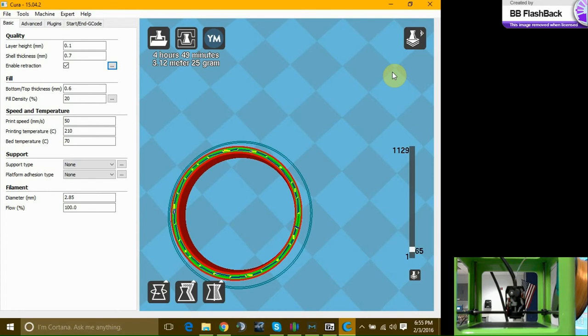25. So that's if you want to save weight, but then you'll be losing strength in a certain direction, because it will give a different pattern in the middle. 100% fill will have a plus 45 to a negative 45 pattern, 90 degrees off each other. So you have one layer, a unidirectional layout, where your filaments will do a zigzag in one direction, and the next layer it will do a zigzag 90 degrees of where it was before, and then repeat that pattern. It gives a nice lattice look.